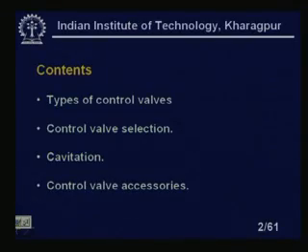Then we will study the control valve accessories. There are various accessories, but the valve positioner is one of the most important things we must learn, because valve positioners will eliminate the hysteresis of the stem of the valve, as well as make precise control of the position, which was not there.